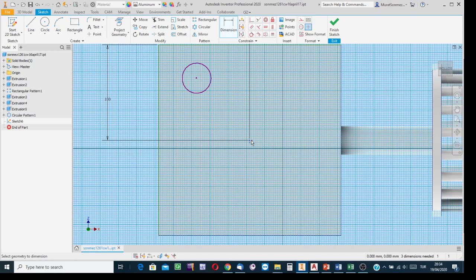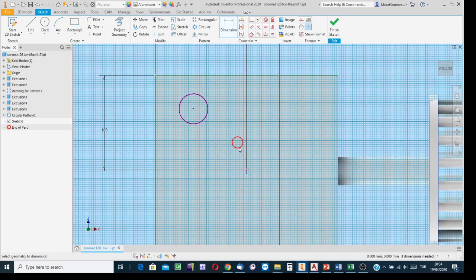Since it is the center of the distribution, for having the base of the member at the correct place, input its radial coordinate. Dimensional constraint, indicate the circle or its center, whichever you like. Indicate the other point, and then you know the trick.